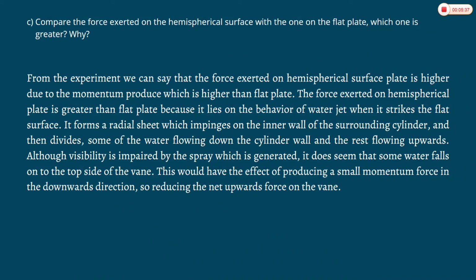So C, compare the force exerted on the hemispherical surface with the one on the flat plate. Which one is greater? Why? So from the experiment, we can see that the force exerted on the hemispherical surface plate is higher due to the momentum produced, which is higher than flat plate. So the force exerted on hemispherical plate is greater than flat plate because it lies on the behavior of water jet when it strikes the flat surface.